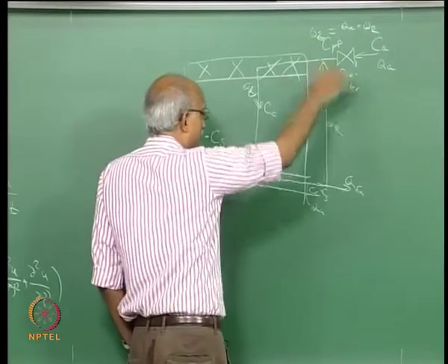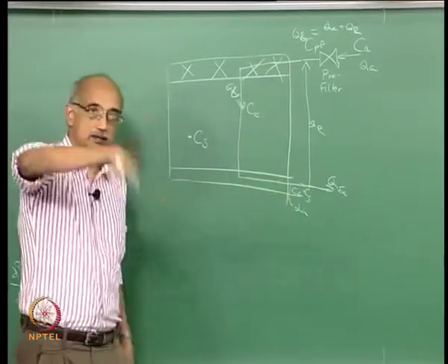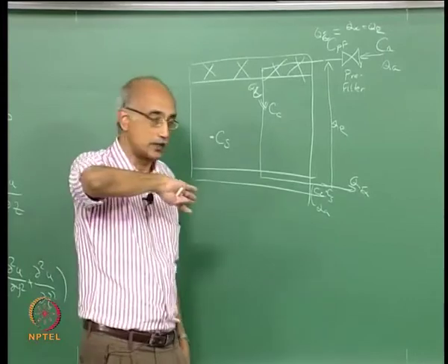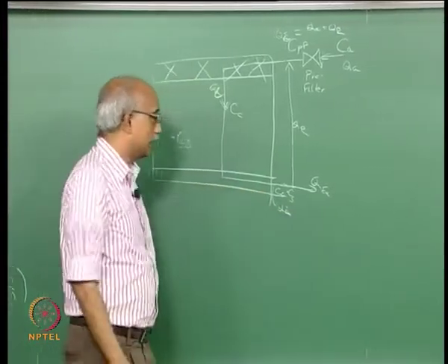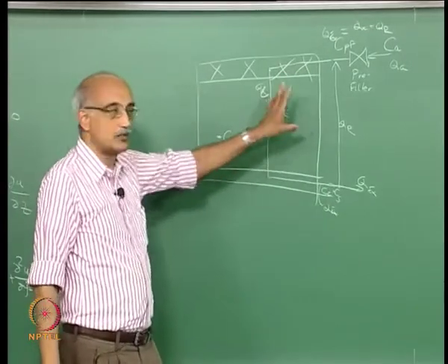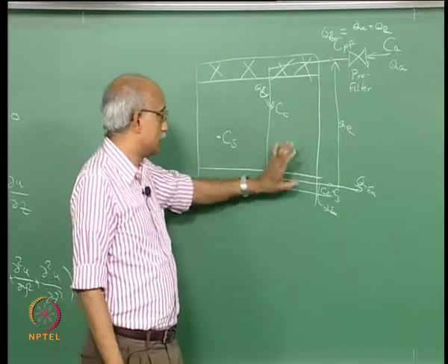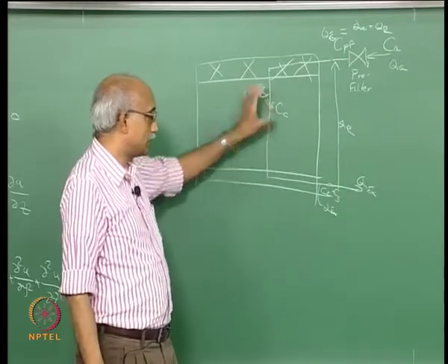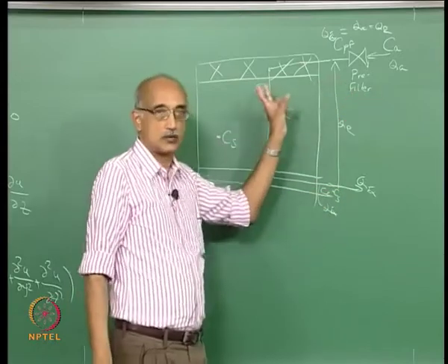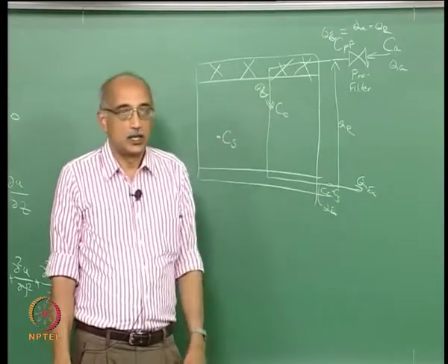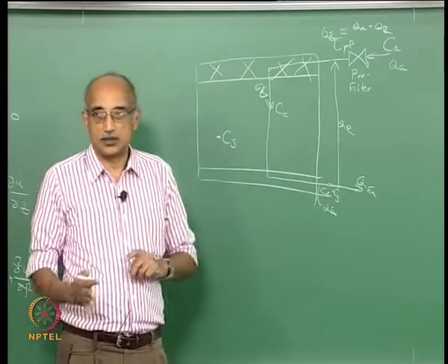because it's basically a loop in which you are taking flow and redirecting it to enter the clean room back in a recycle mode. So here again this is going to change to a Qi, and again you are going to keep taking some fraction of it, and so under steady state conditions the total flow rate that enters the clean room is going to be whatever you are recycling plus whatever is entering as makeup air. So this is the overall flow dynamics for the clean room.